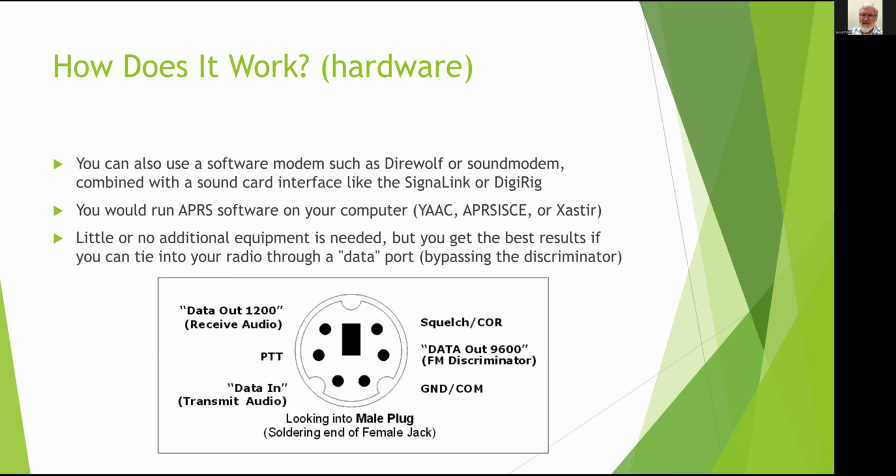Systems like the DigiRig and SignalLink are kind of weird that way, because you tell your software that it's using Vox, but it's not really using Vox on the radio side. The SignalLink emulates Vox for keying up the radio, and it actually has a physical cable that keys up your radio and unkeys. DigiRig also physically keys and unkeys your radio, so it depends on that functionality.